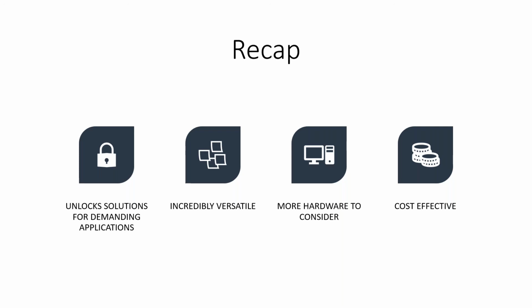It's important to have those options available in line scan, just like with area scan, because no two applications are the same. So having your options with lighting matters, because a lot of applications can be brought over from area scan. And even though you may need slightly more hardware, at the end of the day it does become a more cost-effective solution, frankly, because there are fewer pixels on the camera and fewer LEDs on the board, allowing for a really nice solution, especially when you get to increase the throughput of the machine, if you can increase that exposure time.